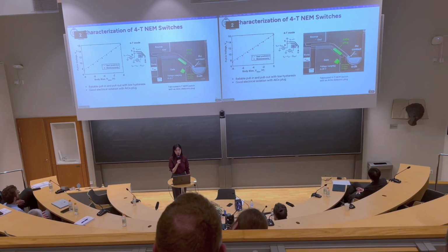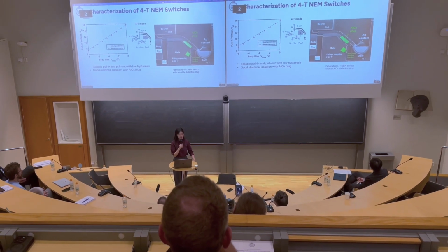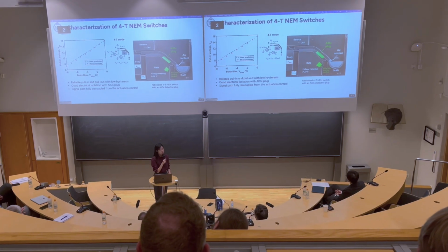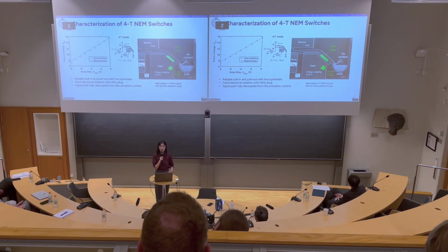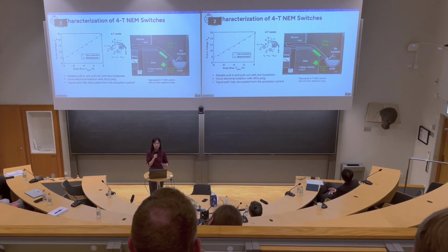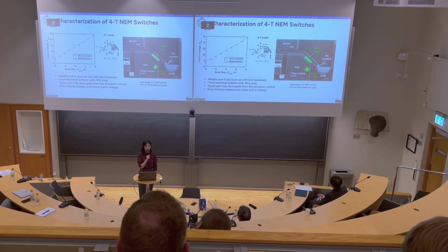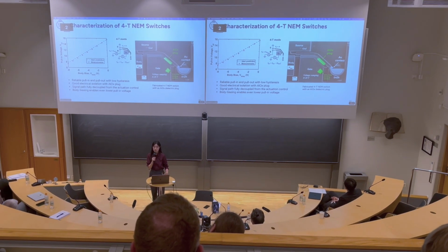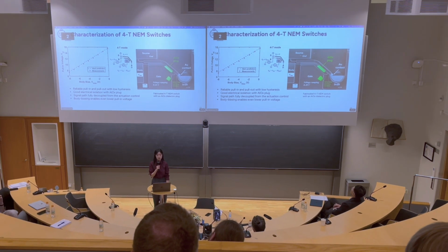The successful application of this analog dielectric bridge also gives us good electrical isolation, and allows the signal path between the source and drain terminals to be decoupled from the activation control between the gate and body terminals. And the lower pull-in voltage also gives us lower dynamic power consumption when we do the switch activation, and it gives us higher energy efficiency.